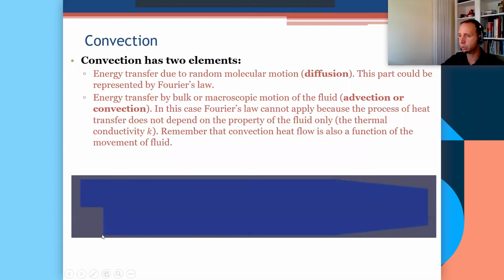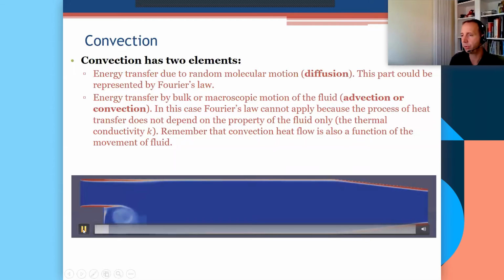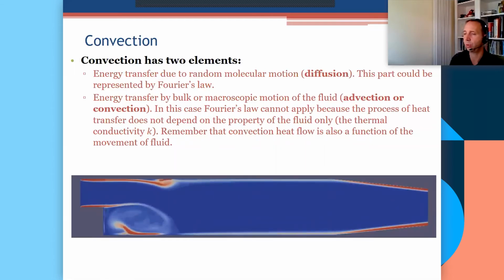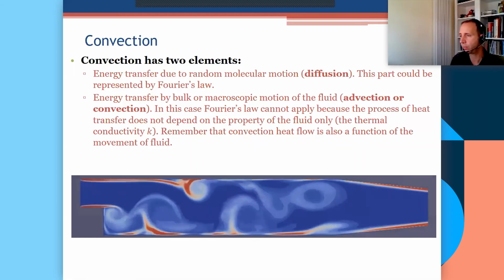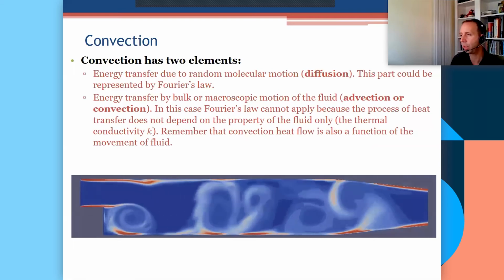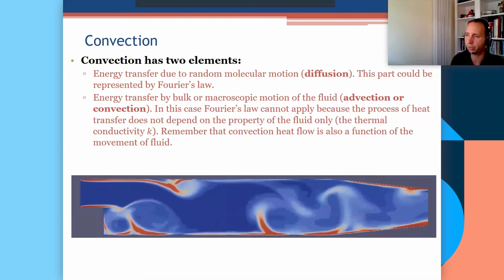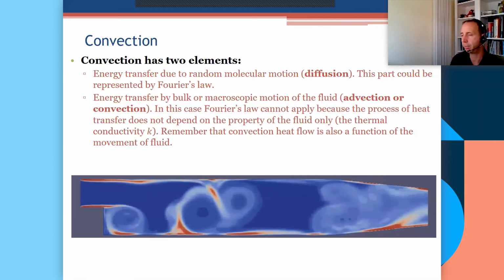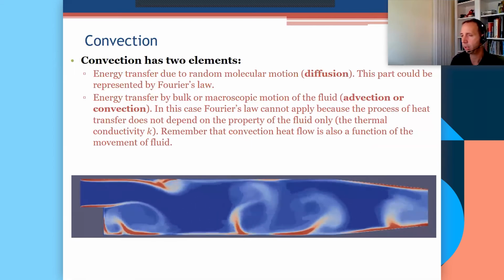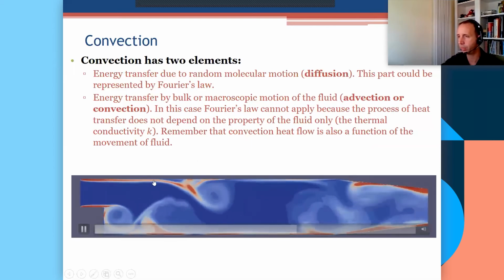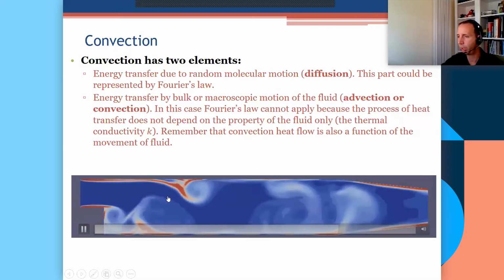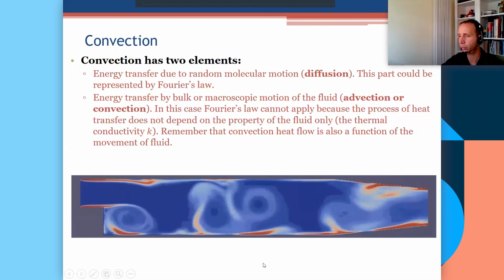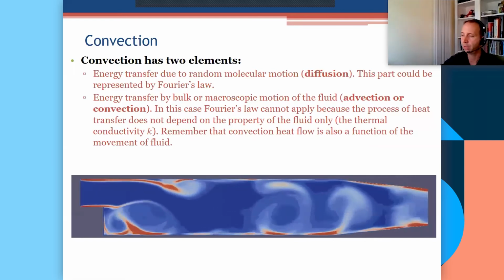Convection. So there's just one video there for convection heat transfer to give you a sense of what it means. We're talking about fluid, perhaps that's colder. Let's say the blue is colder than the surface, which is red. So the cold fluid is interacting with a slowly growing thermal boundary layer, so a layer of fluid near the walls, which are heated up by the hot walls. So that cold fluid is really disrupting that boundary layer, that is a thin layer near the walls. And it's bringing cold fluid in contact with the wall. And that cold fluid effects very high heat transfer.